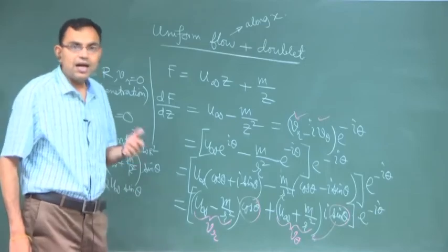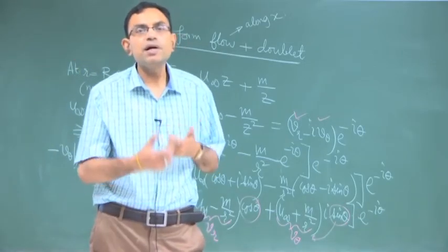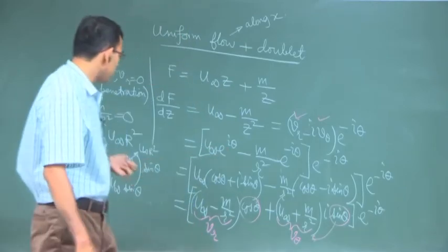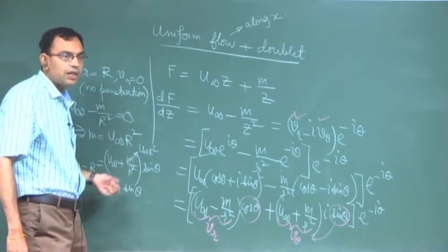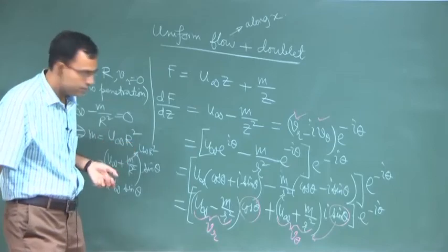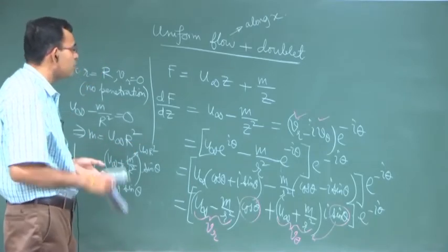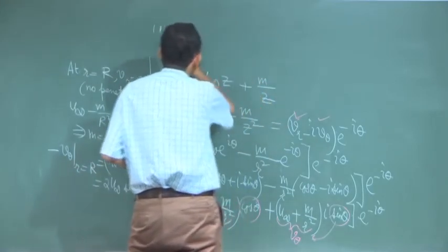So, we can clearly understand that where viscous effects are not present, slip must be allowed. Otherwise, you cannot satisfy the requirements of continuity and momentum conservation on the surface. So, this is the Vr and V theta, we will come to that, but before that it may be interesting to draw the streamlines.